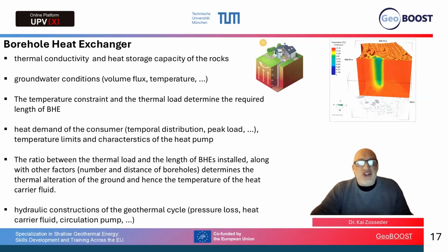So if we have a huge thermal load, then we have to drill a few more borehole heat exchangers, or we have to have a longer drilling distance, more drilling meters, to fulfill the heat demand.